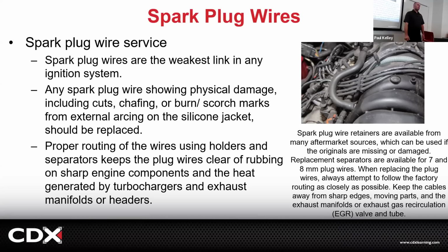Then you get these concerns where it's like, my car has a stumble and a misfire, but only in the rain. My car runs good on sunny days and it runs bad on wet, rainy days. And a type of concern like that, there's a good chance that it's something like these secondary wires or the cap or rotor that have some breakdown of the insulation, and as soon as they get wet, that's just enough to make it arc right here to the valve cover or something.